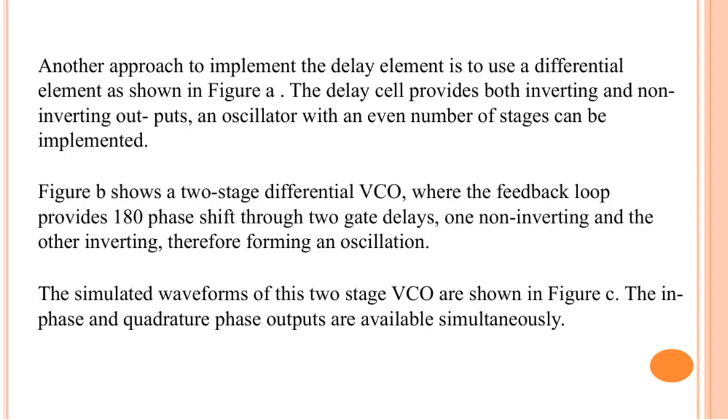Here, we're looking at an alternative way to implement a delay element by using a differential element, as illustrated in Figure A. This delay cell is versatile because it provides both inverting and non-inverting outputs. Thanks to that, you can build an oscillator with an even number of stages, which is not typically straightforward.